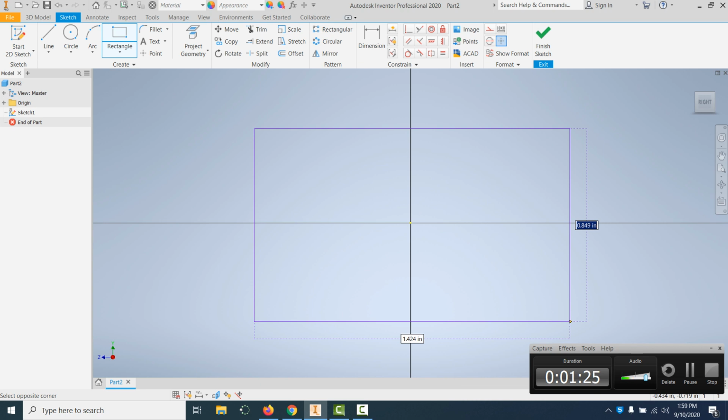So in the original drawing, we saw that the rectangle was 15 inches tall. So I'm going to input 1, 5 on the keyboard, but then I need to jump down to the other number at the bottom of the rectangle. I need to use my tab key to get there. So I did the 1, 5, then I'm going to hit tab, and it goes off the screen.